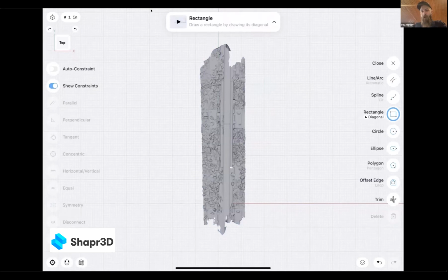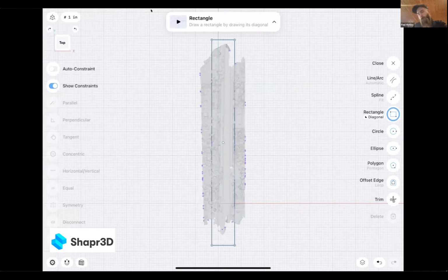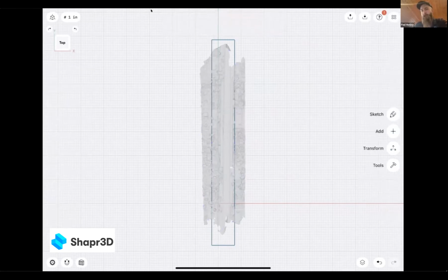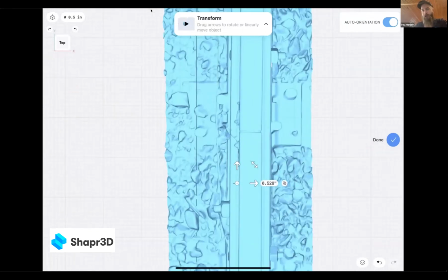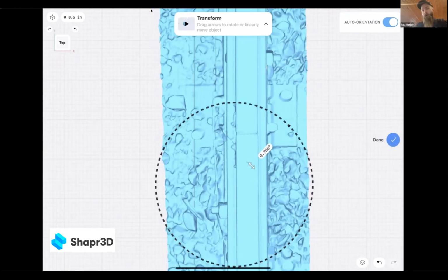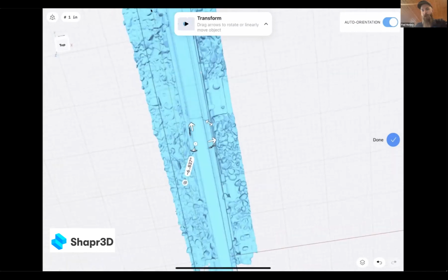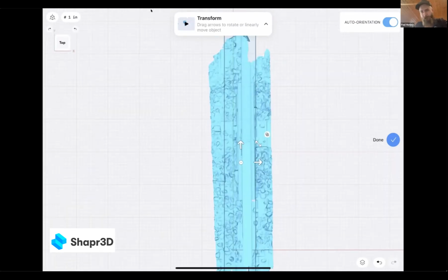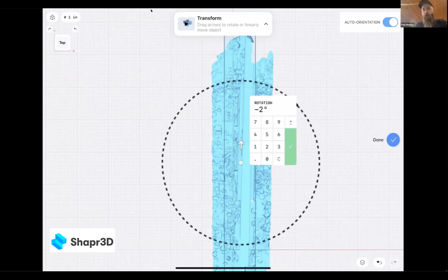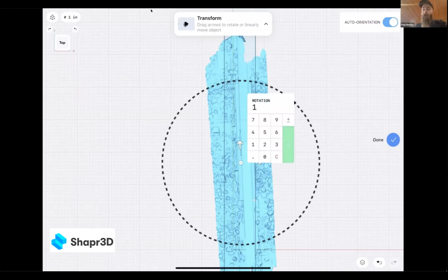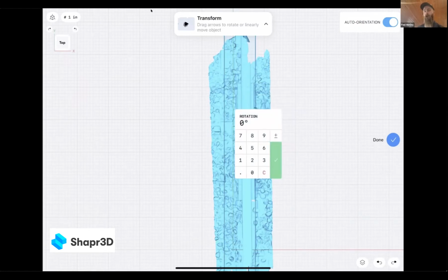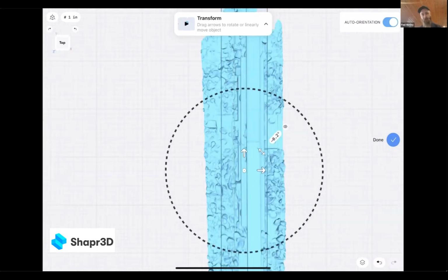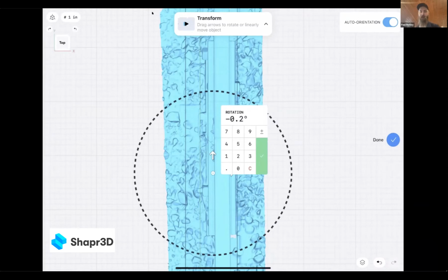Now we can actually start sketching out geometry. One of my findings is that with this type of software, as opposed to using a plugin inside of SOLIDWORKS or DesignX or the tools in Artec Studio, we do have to change the way we do our reverse engineering ever so slightly. Shaper 3D is really built around building out 2D profiles, pulling them into solid objects, and then pushing, pulling and manipulating those for various geometry creation, as well as using those solid objects as sketch profiles.